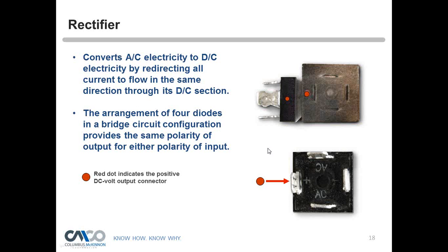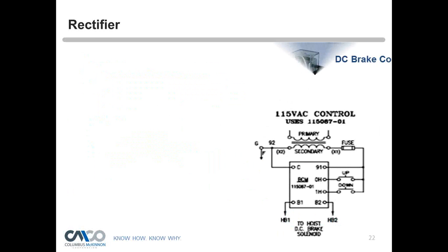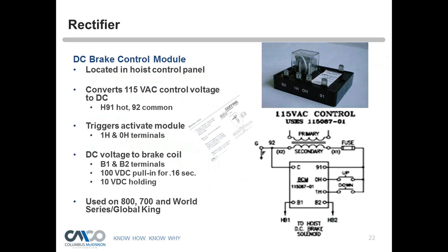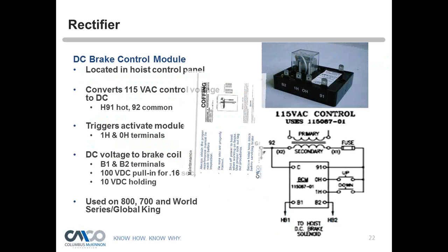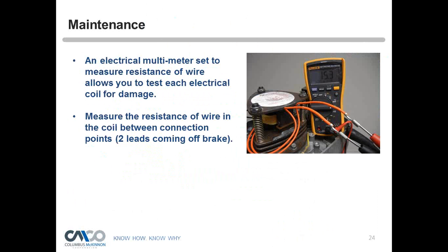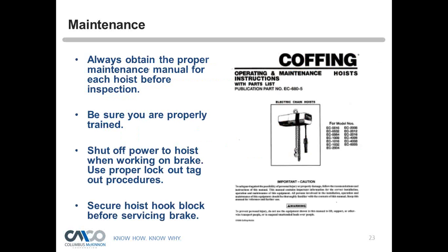Peter, just really quick, it could be possible that he's asking if there are different spring rates for the DC brake, just like with the AC brake. Yeah, definitely. Those springs are sized to apply enough pressure, so you just do not want to get ordinary springs. The springs are sized according to what horsepower the motor is and how much weight it needs to hold. Okay, got it. Thank you.